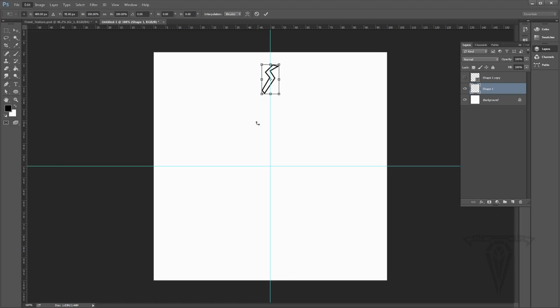And this is very important you do it this way, because this is going to create a duplicate of the object as well as transforming its position. So I'm going to take this little center point and bring it down to where it's locked into place at 50-50 right there. So 50-50. And I'm going to click and drag this on the corner here.